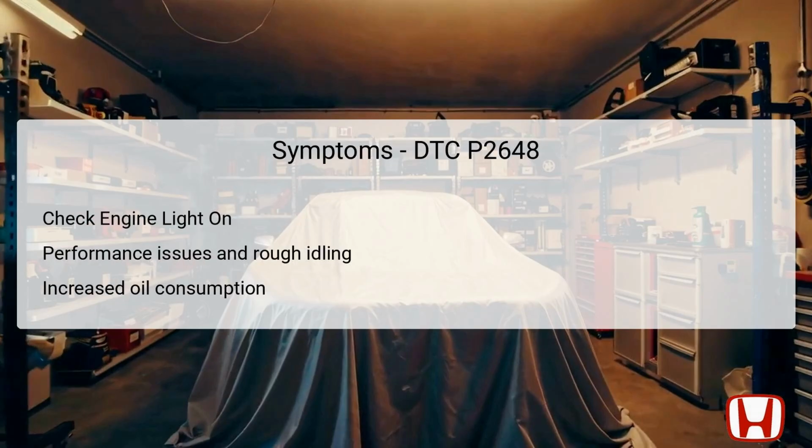Symptoms associated with DTC P2648 can significantly affect the driving experience and vehicle performance. One of the most common signs is the illumination of the check engine light, indicating that the onboard diagnostics have detected a fault. Additionally, drivers may notice performance issues such as rough idling, diminished acceleration, or overall engine sluggishness due to improper valve timing.